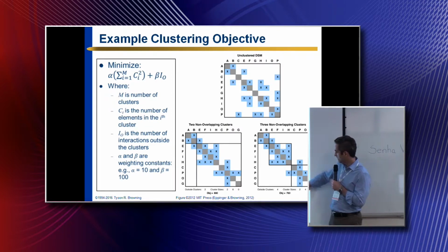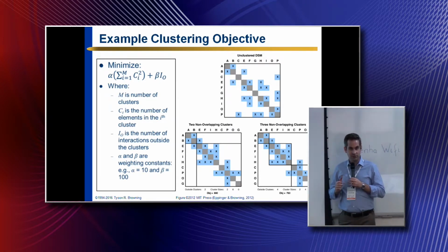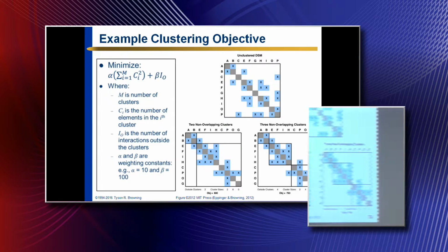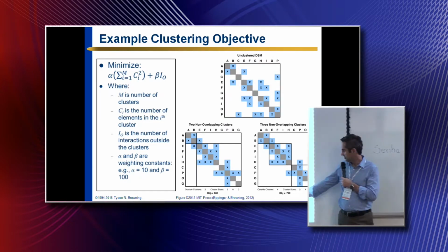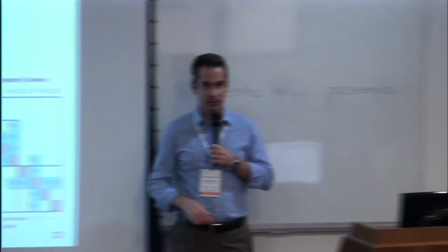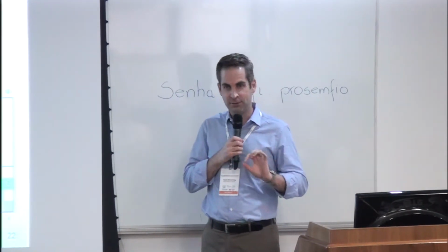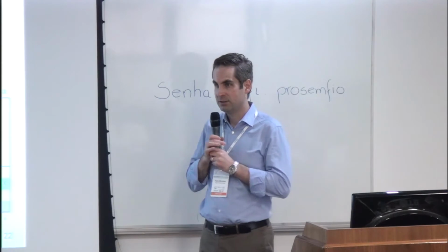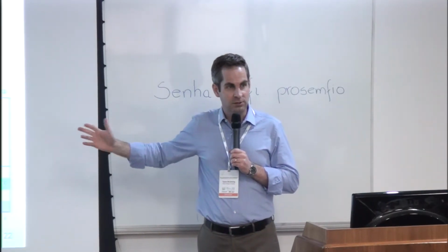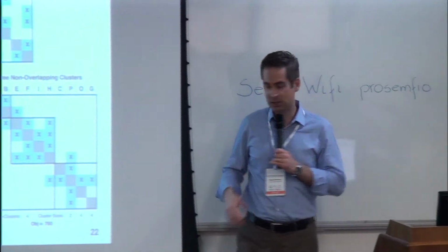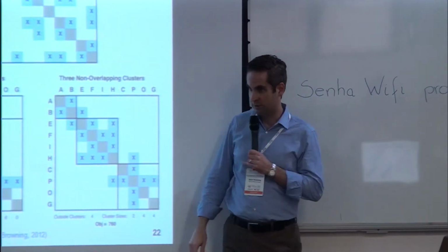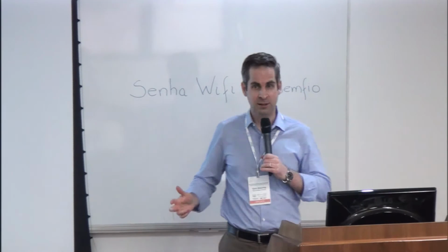And notice here, it's mainly because we took that 8x8 cluster and broke it down into two 4x4 clusters, which, since the size of the cluster is penalized quadratically, taking from 8 to 4 is a big improvement, despite the additional penalty of having now two more marks outside of the cluster boundaries. So you see, clustering is not really so simple at times, and this is just a binary DSM. So how do you start accounting for different weights or importance levels among the relationships, or different needs for components to be together or to be separate in different modules?